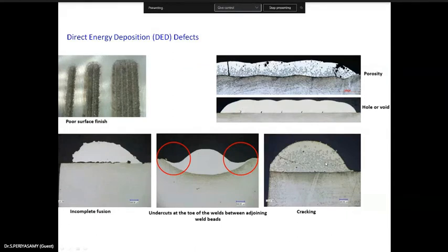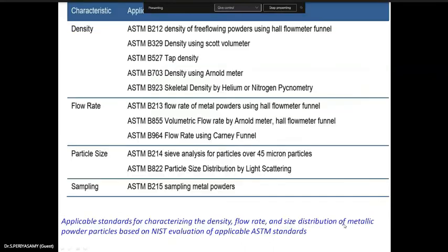If in the formula that value is less than a particular value, you can get a dense packing of the material. Otherwise, it will have enough voids and porosity. It will be bulky. Even at the particle size, we may have a larger number of pores and voids. In that case, its strength may be reduced. Depending upon the application, in a high risk area, this will be a problem. So here you have a layer formation, and in between you have dots, then voids, etc.